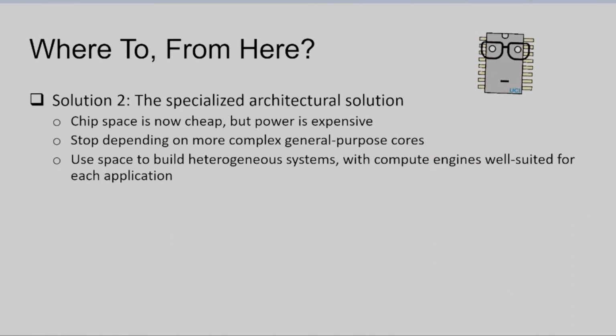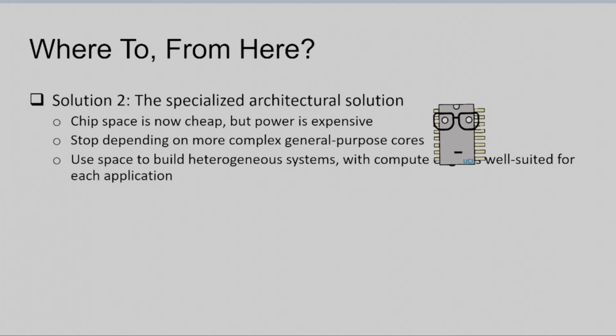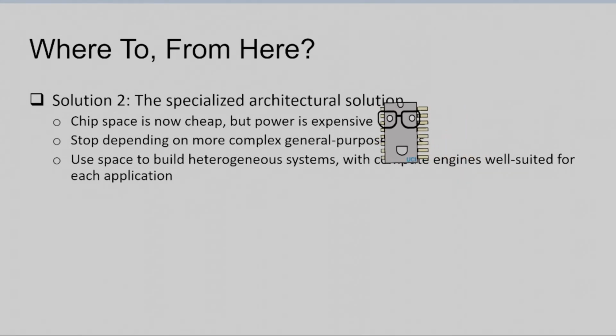The second solution, not the software solution, is the specialized hardware solution, at least from my point of view. The hardware solution comes from the observation that the chip space in terms of transistors is now very cheap because of Moore's law, et cetera. But power consumption is expensive, not because electricity is expensive, but because of heat density.